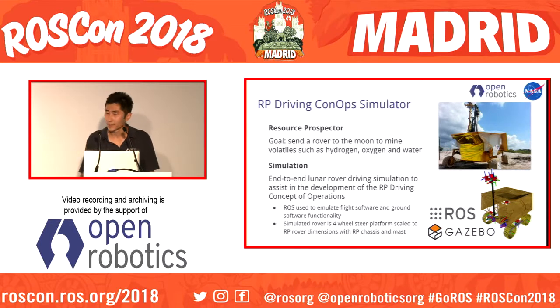In the image you see on the right, that's a prototype RP-1A. It's built on top of the KREX mobile platform. It's got active suspension, and each wheel can be controlled individually. It's got hazard cameras all around the mobile platform, looking at its wheels in case it gets stuck. There's also another camera looking out the back. On top of the rover, there's a mast that carries a stereo camera pair mounted on a pan-tilt platform, so you can look around while the rover is being driven.